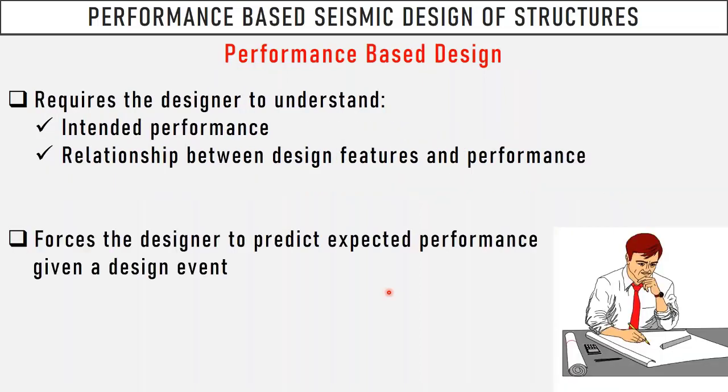And once we change our mind to performance-based design, the designer should understand the performance, in a way, how the building will behave after the expected seismic action.